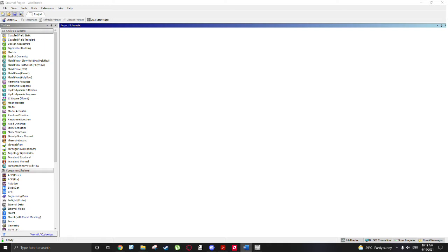The root of the problem more often than not lies in the interface between the fluid region and the solid heat sink. Today I'm going to show a very simple technique to enclose your heat sink in the fluid using only SpaceClaim. This is very easy and should eliminate any inconsistencies in the interface between the solid and fluid that ultimately end up resulting in simulation failures more often than not. This is the culprit that most people run into, the interface between the fluid and the solid.